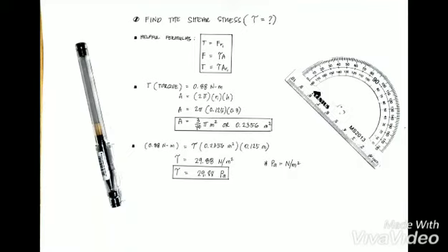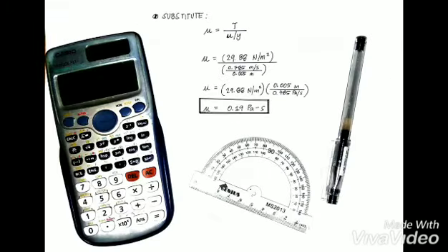And as for our final step, we are now ready to solve the problem by finding the viscosity. So we just need to fill out the shear stress and divide it all over the velocity divided by the thickness. And our final answer is 0.19 pascal second as the viscosity of the liquid which fills the space between the cylinders.